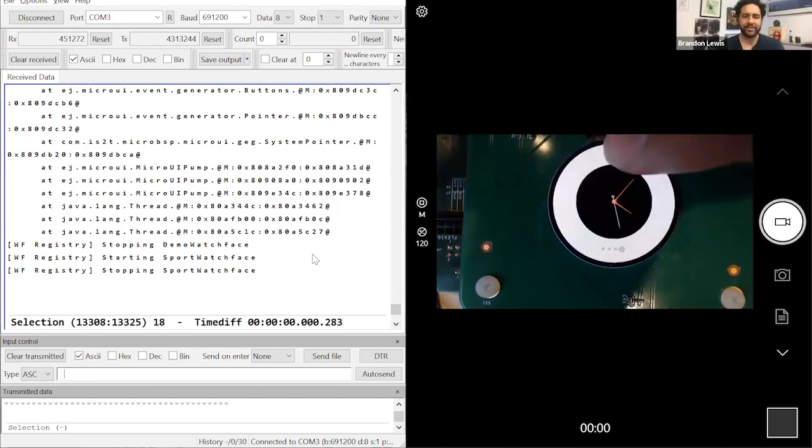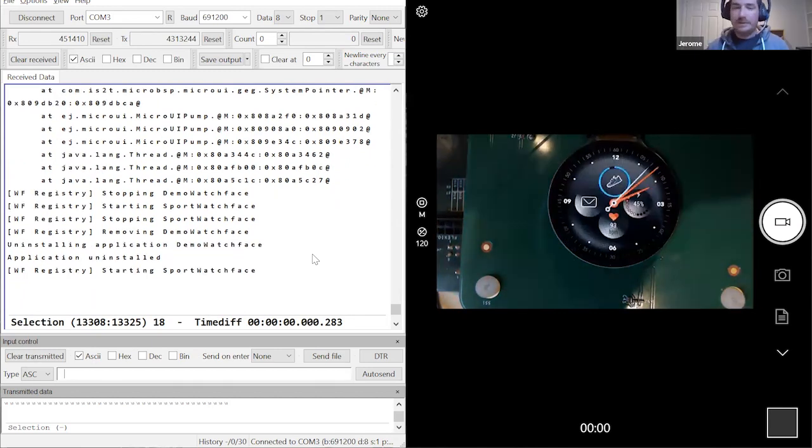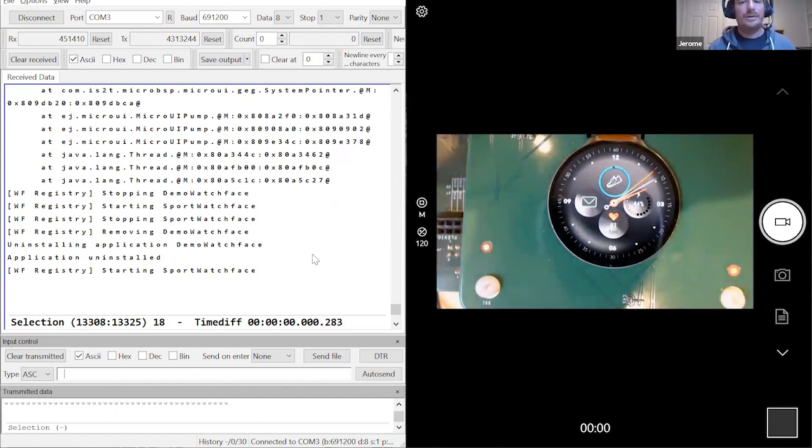That's great. So that's a typical issue you can have with microcontrollers in C. If you do the same thing, you get a crash of the system. You could use an MPU to prevent any kind of illegal memory access, but usually it's difficult to configure. It's not very dynamic. If you add new threads, etc., you need to modify the configuration of the MPU. So here it's built into the system. We have this kind of virtual MMU or MPU that will help you to debug your issues.